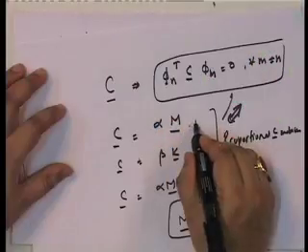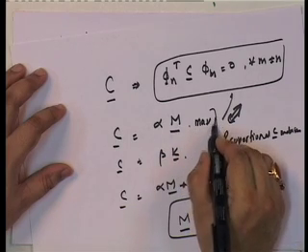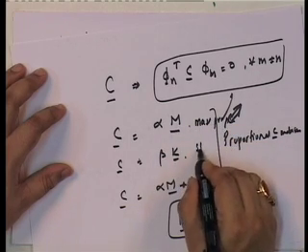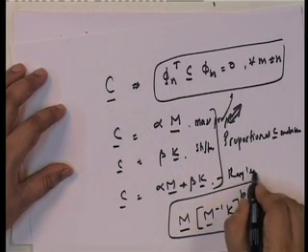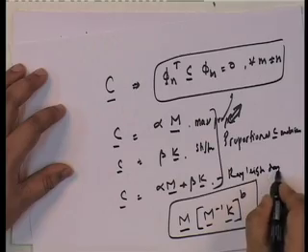So, I can actually write down another, this is known as mass proportional, stiffness proportional, this is known as Rayleigh damping, okay. And we have another C matrix which would ensure this, and that C matrix is of this form.